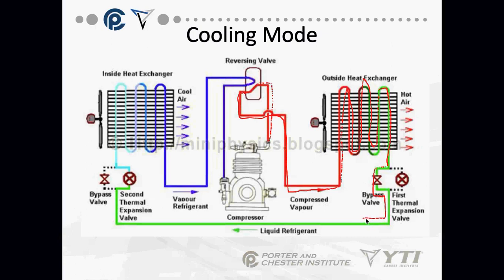At this point, I have a liquid refrigerant that is flowing in this direction towards my indoor coil and my metering device. This is like a standard air conditioner. I come through my metering device, I drop the pressure, I start boiling off the liquid refrigerant, I'm absorbing heat, because that's really what a boiling off refrigerant does, absorbs heat. I now have my superheated vapor. I come back through the reversing valve, and I come into my compressor suction line. Standard refrigeration cycle. With me so far?